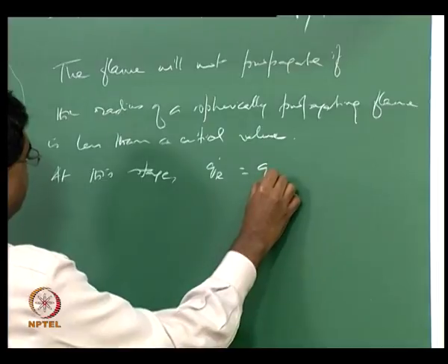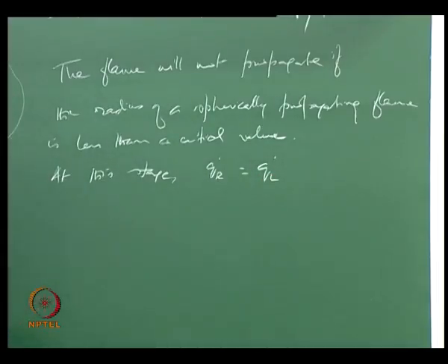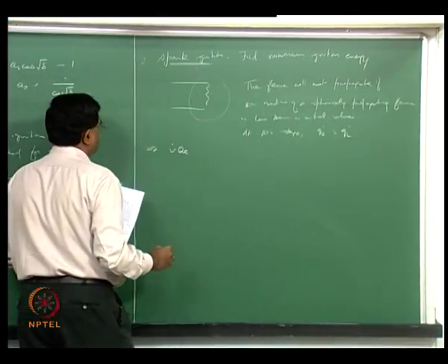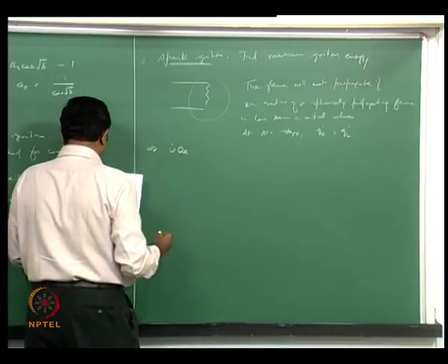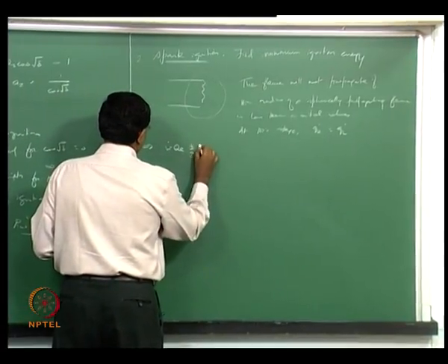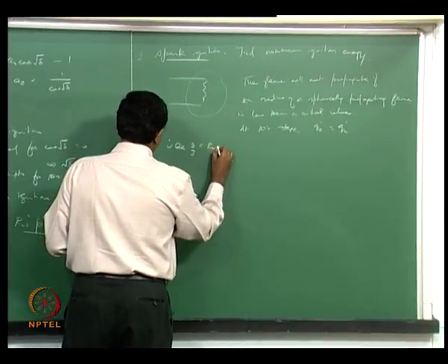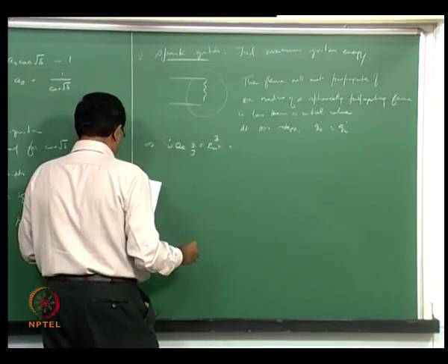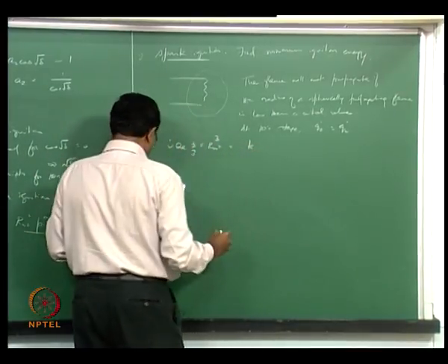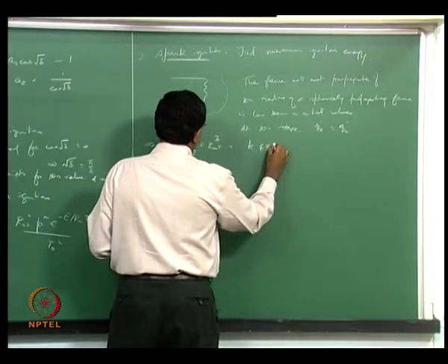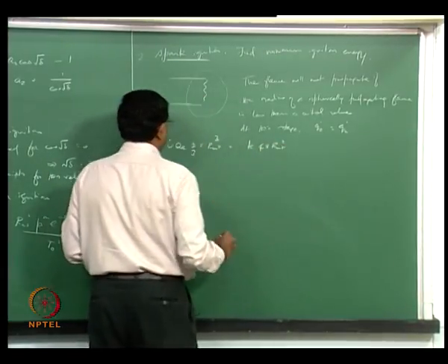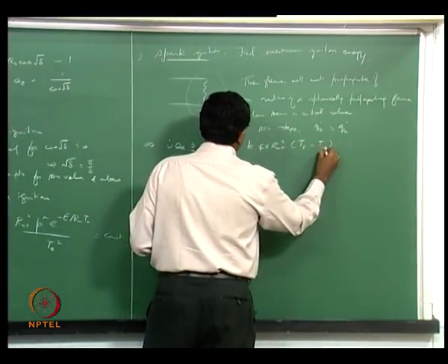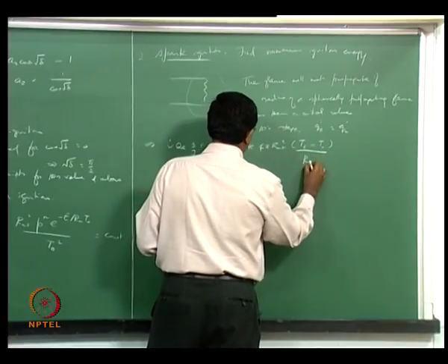Q_R dot equals Q_L dot, and that is to say W dot heat release, so reaction rate times heat of reaction, that is heat release rate, times 4/3 pi r crit cube, should now be equal to conductivity times 4 pi r crit squared, that is the surface area, times (Tf minus T naught) divided by r crit.